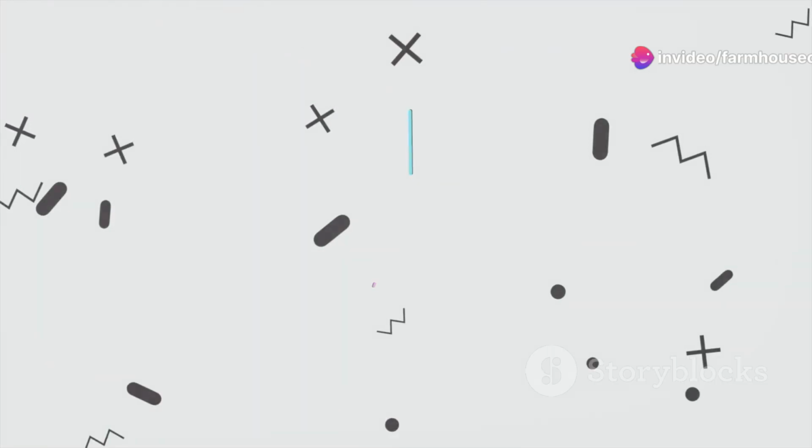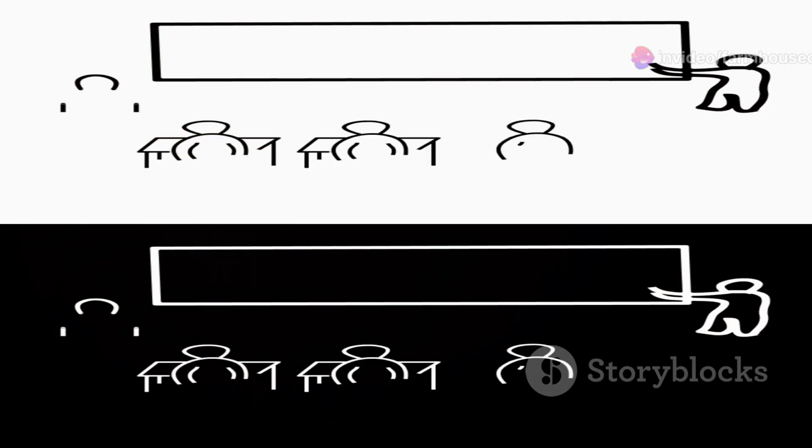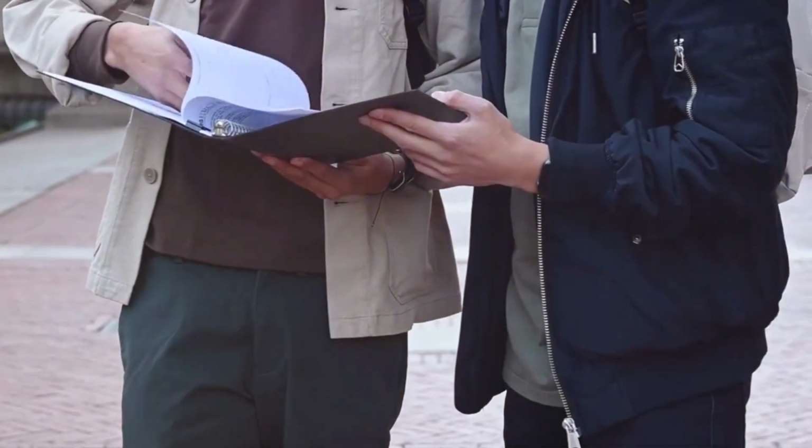Section 4. Grouping terms for simplification. The power of K-maps lies in grouping adjacent cells containing ones. These groups help simplify the Boolean expression. We can group cells horizontally or vertically, but not diagonally. The size of the group matters. We aim for the largest possible groups, as bigger groups lead to greater simplification.